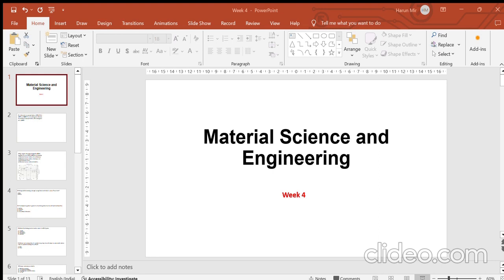Okay, so we have some questions from the last class that we had not done yet, related to vacancies and the number of vacancies and related energy formation. First, we'll try to do one of the numericals on that. It says that in iridium, the vacancy fraction is given by 3.091 times 10 to the power minus 5 at 1234 degrees Celsius, and then we have another concentration of vacancies given at the melting point. So you have to calculate the enthalpy of vacancy formation, which is delta HV. We are given the melting point of iridium.